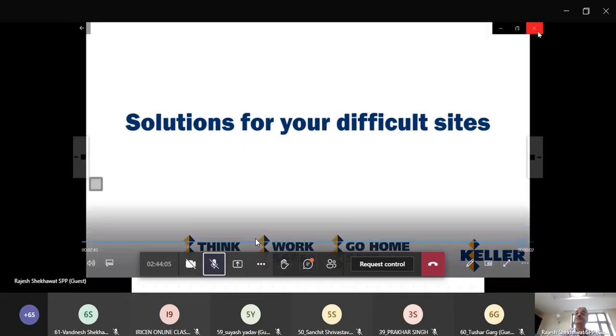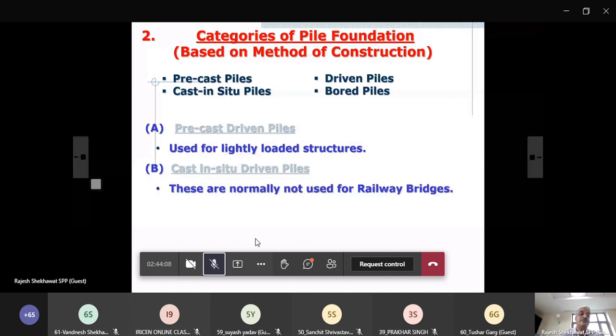Okay? Yes sir. Now, what can be the anticipated problems in this? Sir, quality will not be ensured. Which quality? What part of quality? Sir, the concrete which is being cast, we cannot see what is going inside, whereas in precast all the control parameters remain in our hands. Okay, that is there in every cast in situ method. That is, of course, one of the limitations of every cast in situ system.